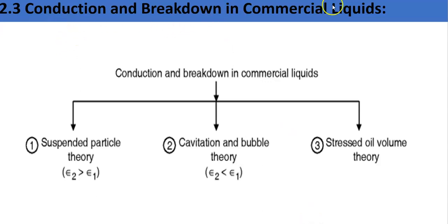So, conduction and breakdown in commercial liquids. We are starting with commercial liquids first, and after that we will discuss pure liquid. For pure liquid there is only one theory, and that is field aided emission. Now there are different theories for commercial liquids. First is the suspended particle theory, then cavitation and bubble theory. The third is thermal breakdown, which is also mentioned in the syllabus, and the stressed oil theory is also there. So four theories are there.